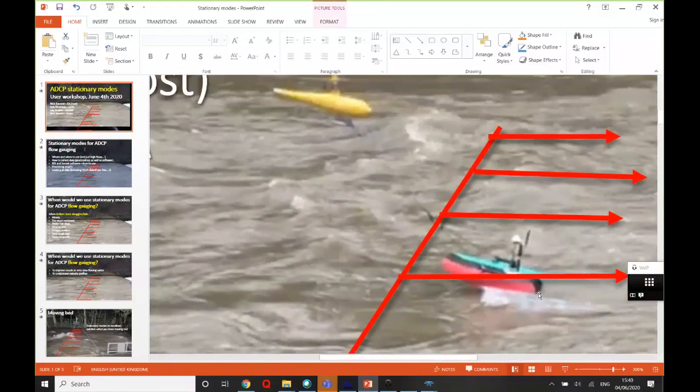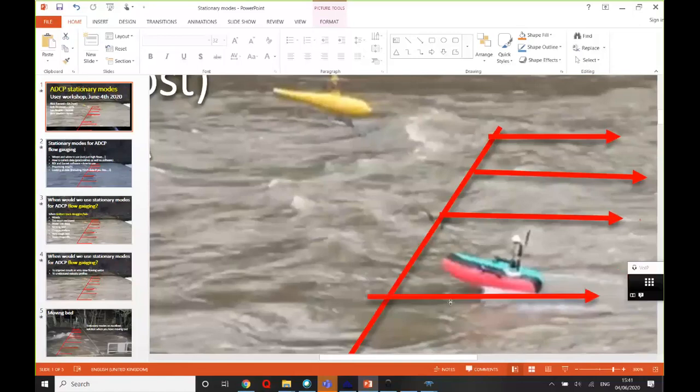So you could move those mounting points, and there's 2 eyes that screw into the board. You could move them more to the middle. So this is the RS5, I think, isn't it? We were really just having a muck about to see what data we got, and any tips, because I have no cableways in my patch, and I certainly don't have cableways in fast flowing water. So tips to try and improve it. Again, the bomb closer to the surface and tethering it. And maybe a longer line between the bomb might help get it a bit lower. And also, the tethering points, you can move them forward or aft as well. So to get that pitch down a bit, you're probably using the aft points, which is in probably a similar place to where you got it tied on.